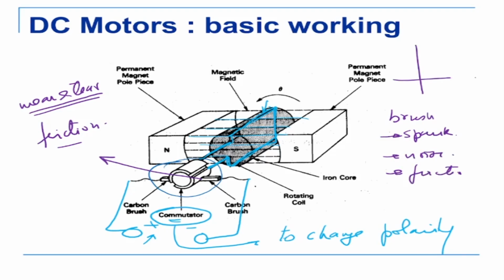So if I'm looking at voltage versus speed of this motor, then it should theoretically be a straight line. But because of this friction, it will become a little bit like this, then become straight, then become like that. So in the starting and the ending portion, because of friction, it will not be a straight line, it will become non-linear there.